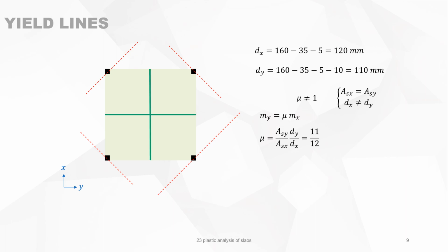Then we take the yield lines. When the axes of rotation cross, they have a point there and a point here. You make an auxiliary line, and then you know that the yield line stops at the edge of the slab, and then the same in the other direction.